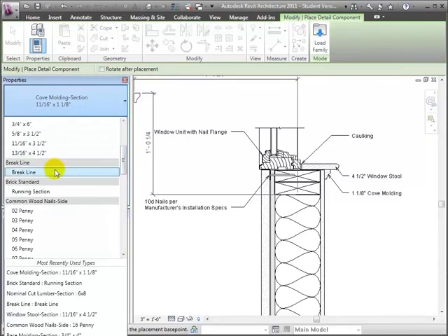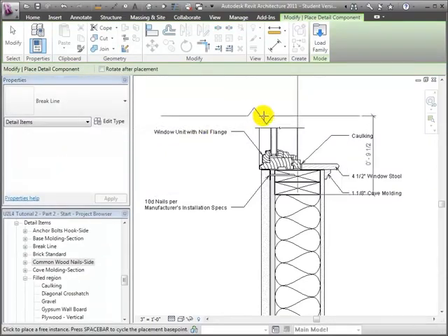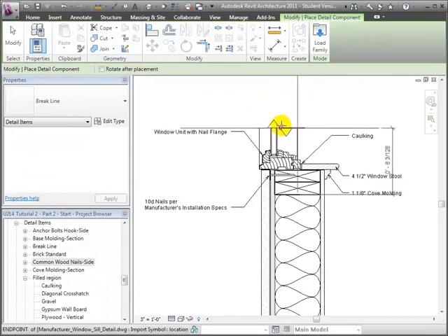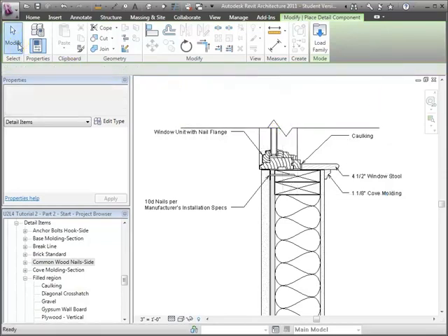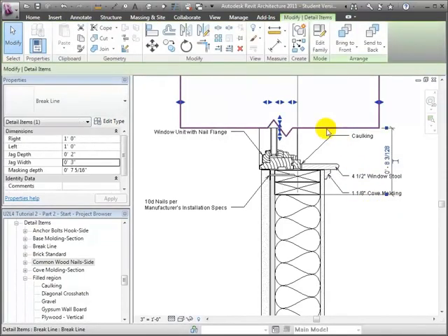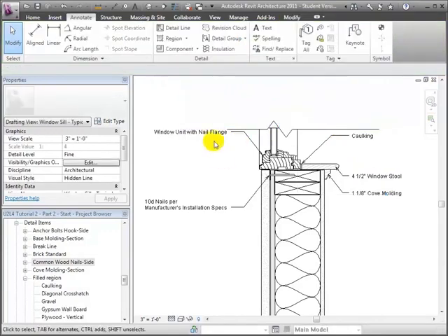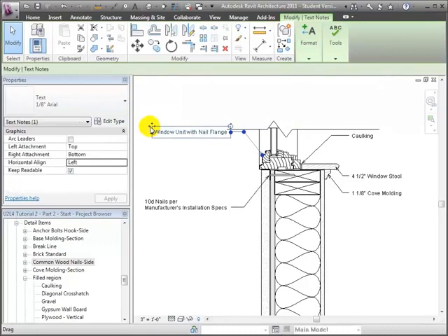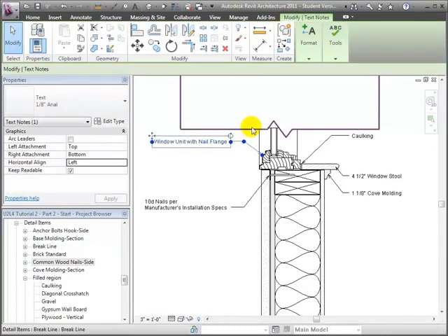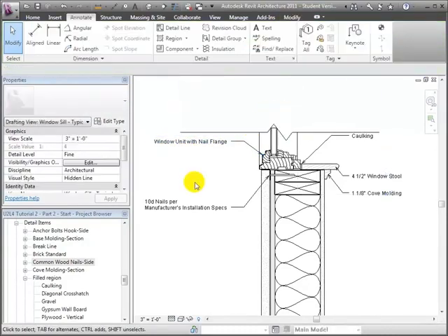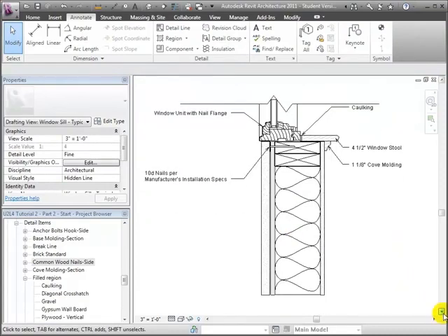The break line really has a line, which is really the cut between the detail and what's going to be shown and what isn't going to be shown. And if I place it, anything beyond that line will be hidden. In this case, let me kind of shove it down just a very little bit. Maybe I'll even go through and just move my text down a little bit so I can bring the break line down even further. What we're doing is indicating just really where the detail stops and obscuring anything beyond that line. Now at the top it didn't make a very big difference.